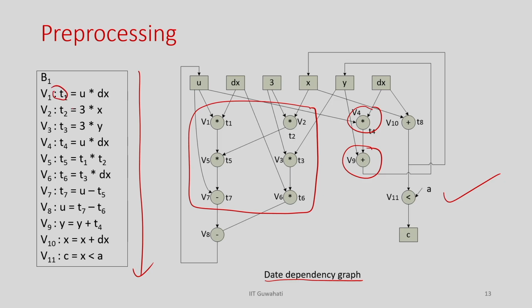Here you understand that this T1 is defined here and it is getting used here, and that is all; for the rest of the time I do not need this. Once this T1 is defined and then used, after that I do not need T1. In the hardware I can remove that value, because I have no use of T1 for the rest of the circuit. So, let us remove that value from the register and store something else. That is how the sharing happens.